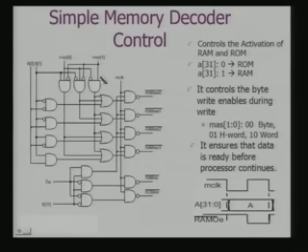That is, depending on the size of the transaction and depending on this address, one or more of these RAM write enable signals will be activated. And this is a way by which your size information has to be made use of, because you need to know for a bus transaction what is the size of the data transfer that is taking place.